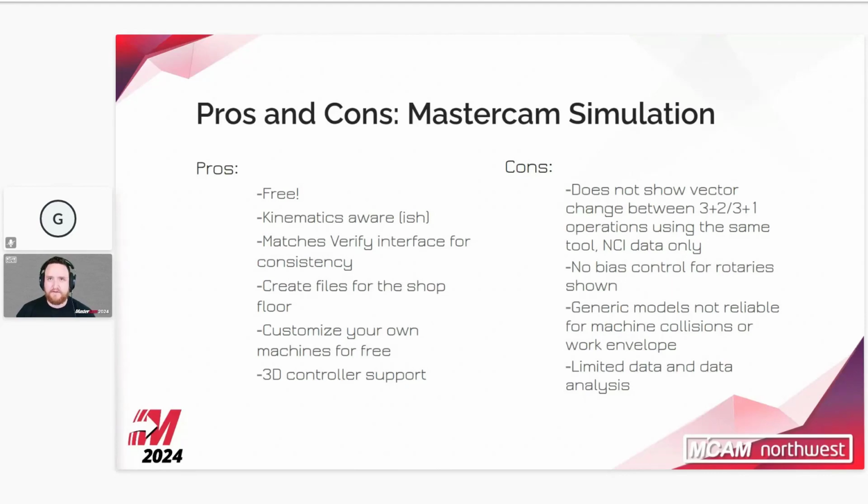So some machines have maybe a trunnion that could swing two ways, and you might want to force it one way to make it so the operator has an easier time seeing what's happening. And we can't really control that with Mastercam simulation. While we might have a post that has a switch that allows us to do so, we can't double check it and verify because since it's a post switch, it's not part of the NCI data and it's not being read into simulation.